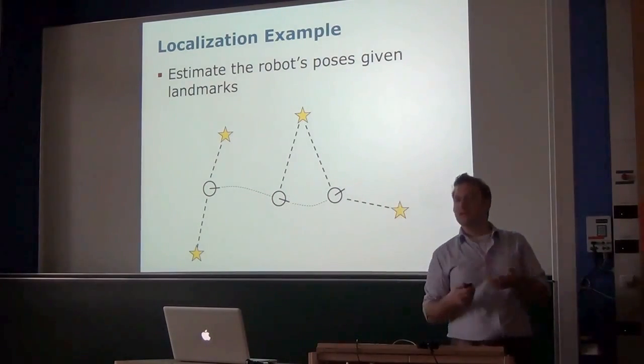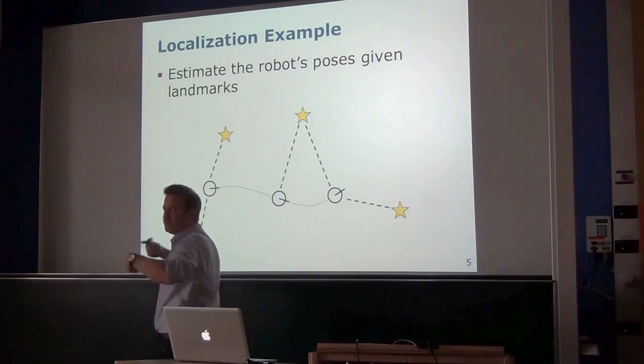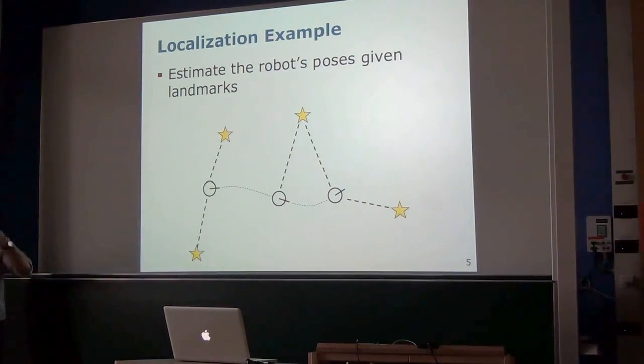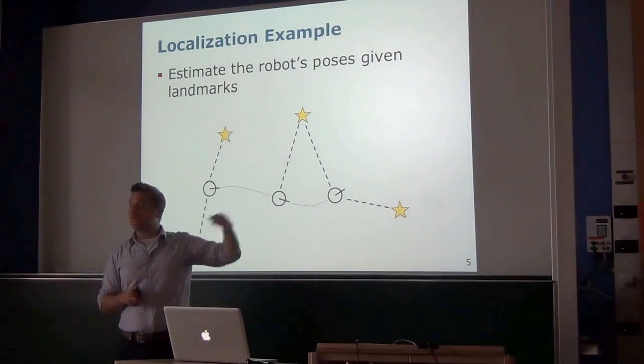but the robot thought that it traveled slightly differently, because what the robot typically does is count the revolutions of its wheels to estimate how far it traveled. And you have a sensor which always gives you relative information. So if I'm standing 2 meters more to the left-hand side, the proximity measurements between me and the wall will be 2 meters short.